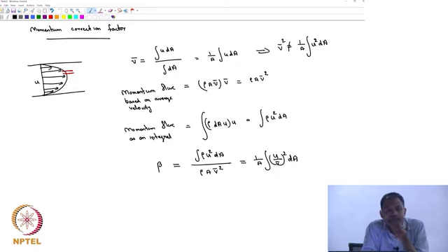Yeah, so where we basically wrote down our force balance, I think on the right hand side we said it's mass flow rate times velocity, so that was really the total momentum in, and I said V is the average velocity. But writing down that expression, we have made an assumption that V square is actually giving you the total momentum in, but that's not really right. There should have been a factor, and that factor is beta. So, in our derivations, we have assumed beta to be 1, and therefore that calculation is not exactly right.